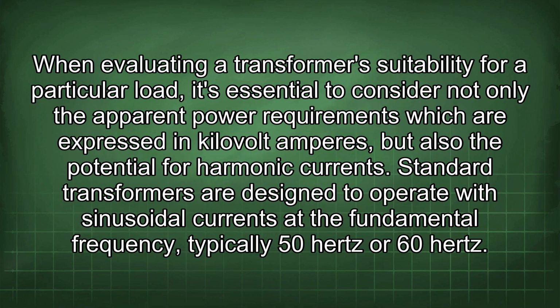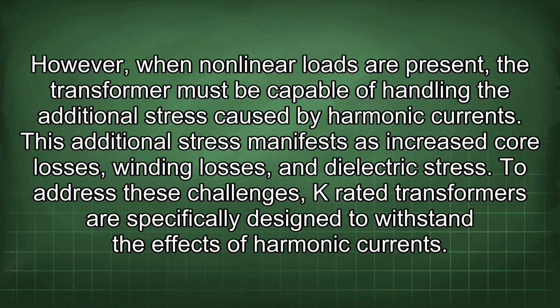When evaluating a transformer's suitability for a particular load, it's essential to consider not only the apparent power requirements, which are expressed in kilovolt amperes, but also the potential for harmonic currents. Standard transformers are designed to operate with sinusoidal currents at the fundamental frequency, typically 50 Hz or 60 Hz. However, when nonlinear loads are present, the transformer must be capable of handling the additional stress caused by harmonic currents. This additional stress manifests as increased core losses, winding losses, and dielectric stress.